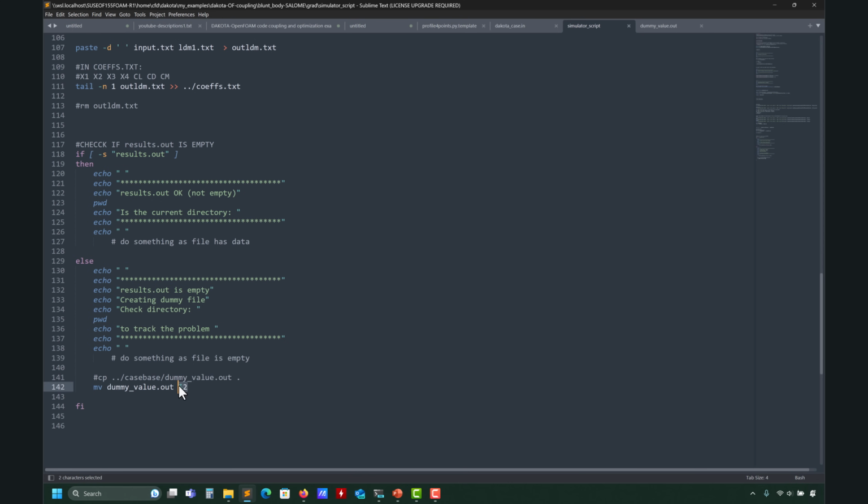Another method would be that you know where it failed, and then you choose a value close to that value, but also a little bit different, to discourage the optimizer from testing that point again, because you know that it is failing there. You need to discourage the optimizer from going to that point, but the value needs to be close because you are moving in that direction. There are many techniques to do that. I have to say the implementation in Dakota does a very good job. I need to update this one also to add that, but for this simple case, this is okay.